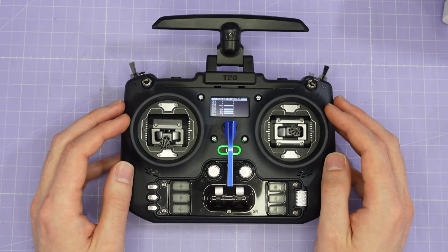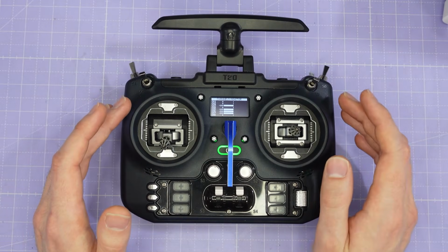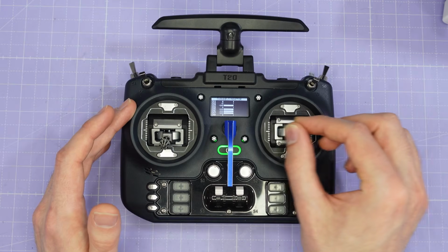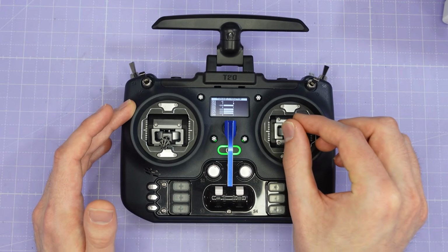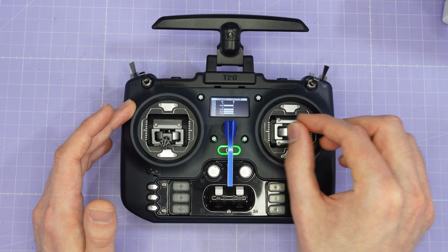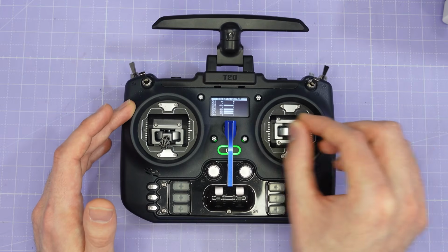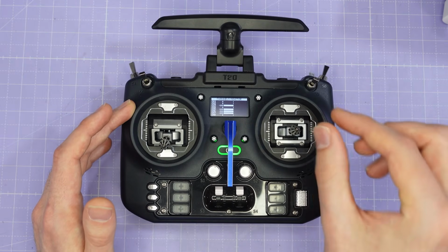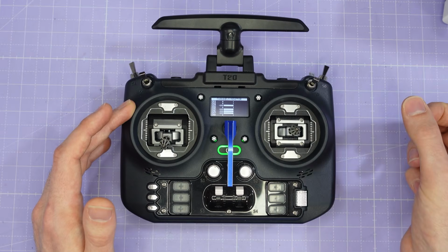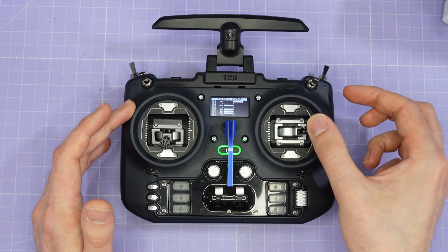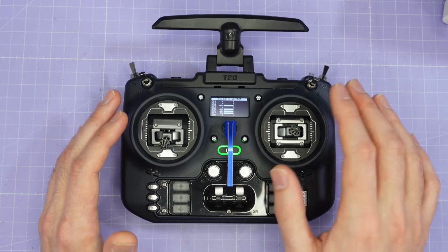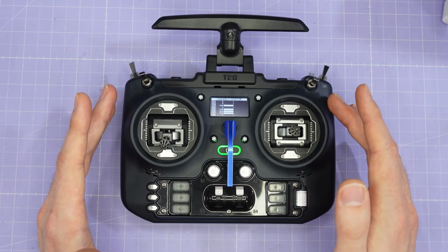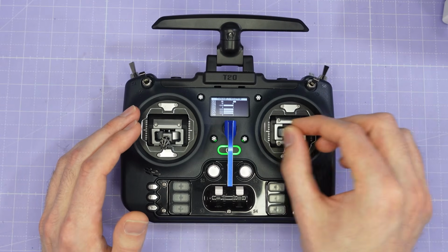There are two things to bear in mind when you're doing your tuning flights. The first is make sure to keep hold of the stick as you're doing your sharp moves. So a sharp move out and back to center is okay. A sharp move left and right where you wobble the stick like this is also good. But don't do this. Don't release the stick and let it bounce back to center, because that is going to create all kinds of oscillations and totally mess up your data for making decisions on your PID tuning. So make sure to keep hold of the stick.